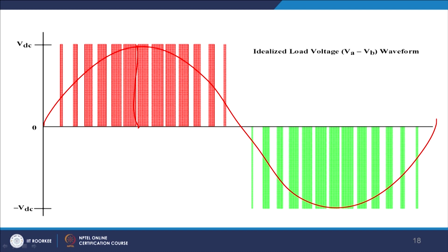And another advantage is that it eliminates a huge amount of harmonics. Why? Because it forms a notch in this, the 0 potential. So, in that way many undesirable harmonics are truncated, and moreover instead of the dominating frequency being shifted after the fundamental to F, it will transfer to 2F.